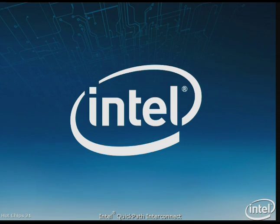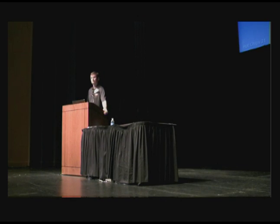Yeah, thank you. So this is Ken Chen from Rambus. It's interesting that in contrast to HyperTransport, you support asymmetric arrangement of the link, but it seems you mentioned that you always form the link pair, like the one direction is equal to the other direction. Is that true? Do you really need that? No. By convention, the links are symmetric in size. But you don't need that. There's nothing that says it couldn't be asymmetrical. And in fact, when in the failover mode, where you have a failed lane or clock failover, immediately that direction will go to half width.